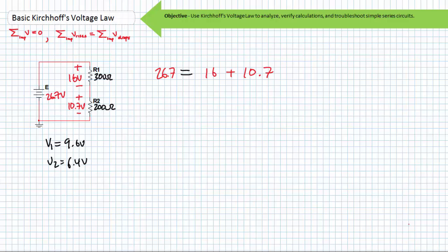Let's give our lab partner a little credit though. Setting up the supply voltage should be easy, as should be ensuring the correct components are being used, as well as instrumentation being employed properly. Let's assume they're not a total doof and are just having troubles building the circuit. These assumptions being made, an equally valid answer to this same question is also this. Check the voltage drop across R2.